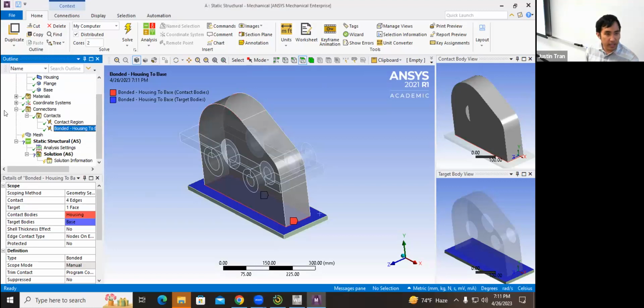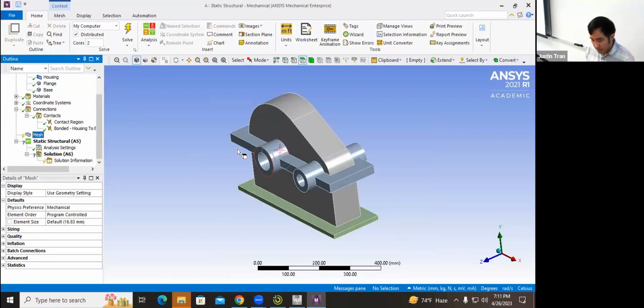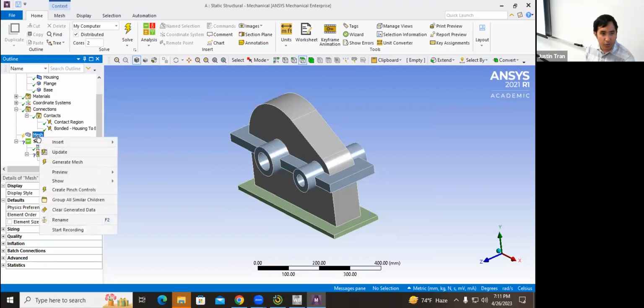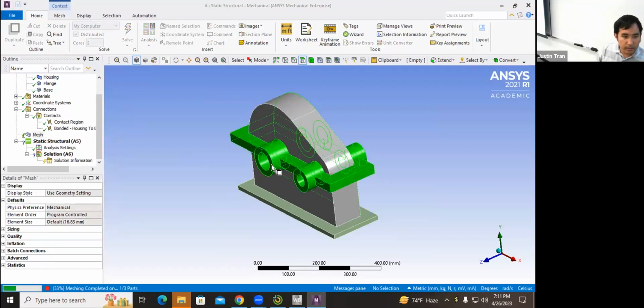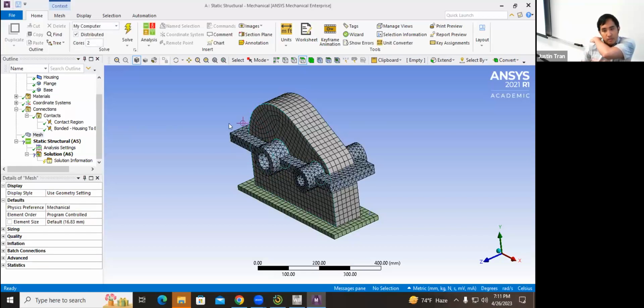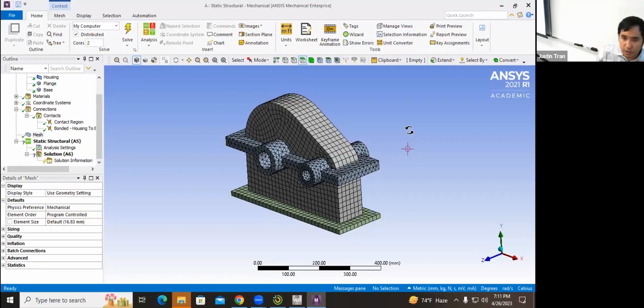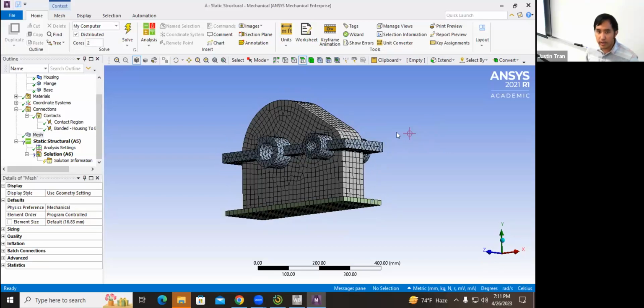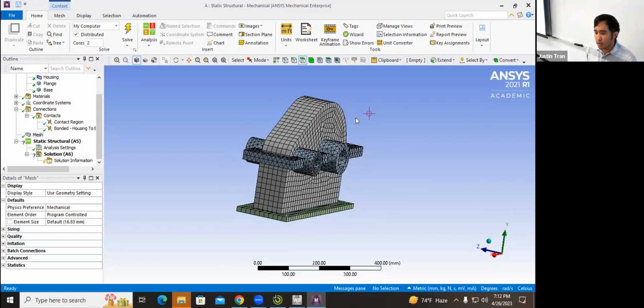Okay. All right. So next step, we're going to mesh. The good thing for this is that we actually don't need that much of a mesh. So let's go ahead and just generate the default mesh here. Okay, let's see what that looks like. All right, I didn't apply any meshing settings, and this is what it looks like. This actually looks pretty good already. We're not really doing a lot of stress analysis here. We're mostly focusing on the resonant frequencies, so we don't need that much of a mesh. But just like always, feel free to tinker with the mesh. You can add settings if you want, but for now, I'm just going to roll with the default mesh.